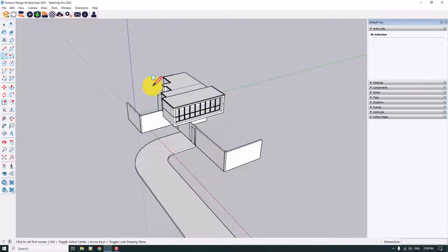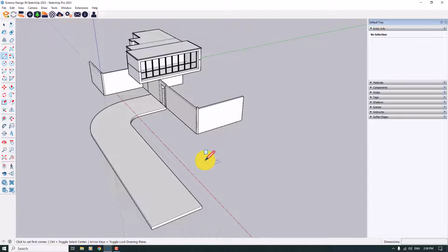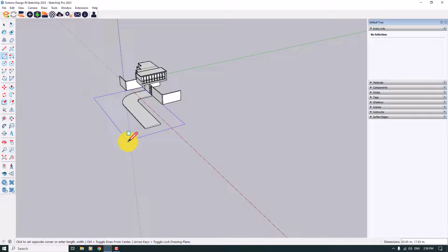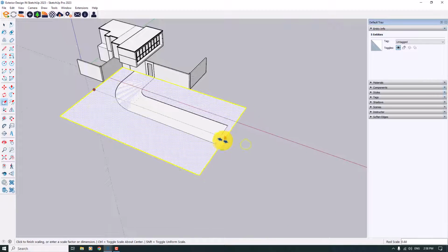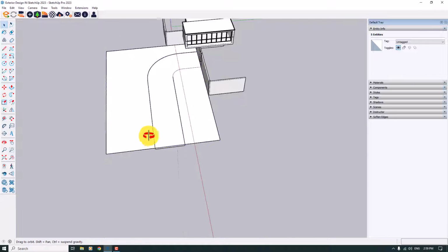I want to expand this area, for example, create some side plan, grasses or vegetation. I will use this endpoint and draw my rectangle like this. Don't worry about the size of it. Click on it, use the Scale option, rescale it like that, and tape measure it from this point, totally about 19 meter, and use Scale to fix it with this point here.